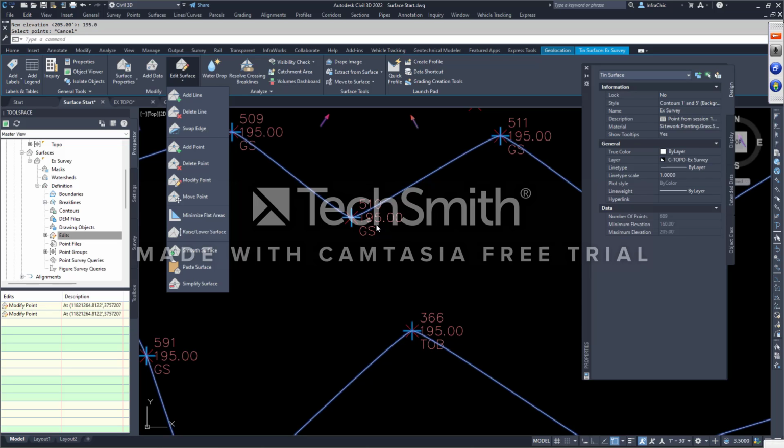There may be a 10 or 15 foot difference. So knowing that, whose surface should I raise or lower? The rule of thumb is the GIS goes up or down to match the survey. You never take your survey and match the GIS. Just don't do it, okay? If you're going to do that, go through all the trouble and change all the points too, okay? But in general, we take the GIS and move it to our data. We do that by raising and lowering that specific surface, okay?